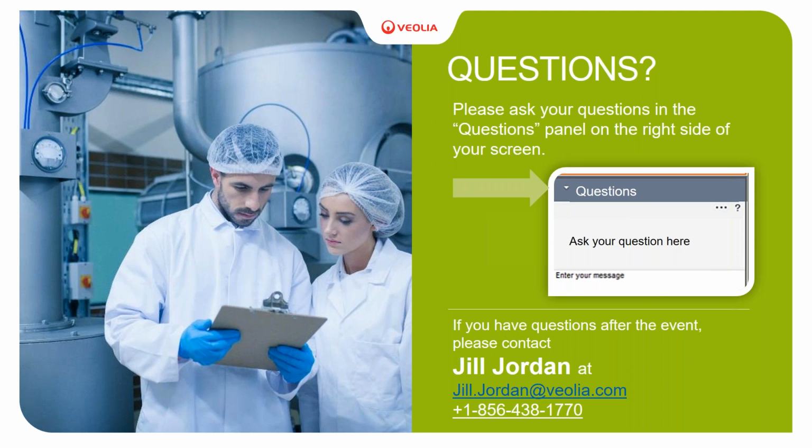I consider the top of the sludge bed to be the level with a TSS of at least 25,000 milligrams per liter or more. So let's say you have 8 sludge sample ports in your reactor, and the top one is 3 feet below the settler. You wouldn't want your sludge bed to grow much above level 7.